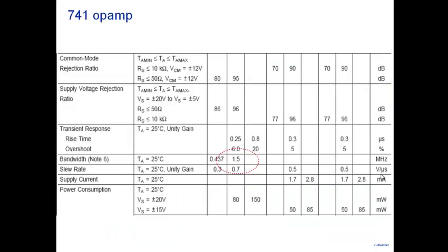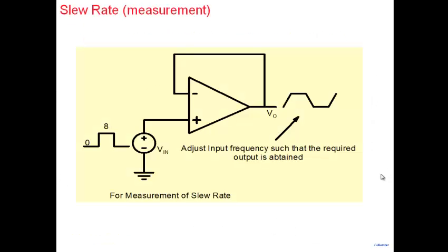Now, that's another thing that you should keep in mind here. Will it bother you? Now think about, suppose I had taken a circuit, and instead of a square wave, suppose I put a sinusoid here, say 10 volt or 8 volt or whatever. What do you expect at the output? A sinusoid, right? Because it's a buffer. So you expect a sinusoid. But then, as you increase the frequency of the sinusoid, what happens to the slope? dV0 by dt? Where does the sinusoid have maximum slope? At the origin, right? It has minimum slope at pi by 2.